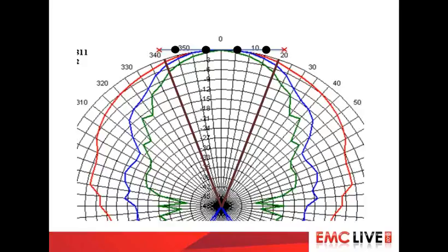So if we follow from our 0 point on the red curve, and let's go clockwise, clockwise, clockwise, until we hit our red cross, with the definition of our zone of interest, we can see that the power density has dropped. What would you say that was? Each one of those boxes represents 3 dB. I'm going to say that it's dropped 1 dB. So we need to compensate for that. So we'll call that a loss.